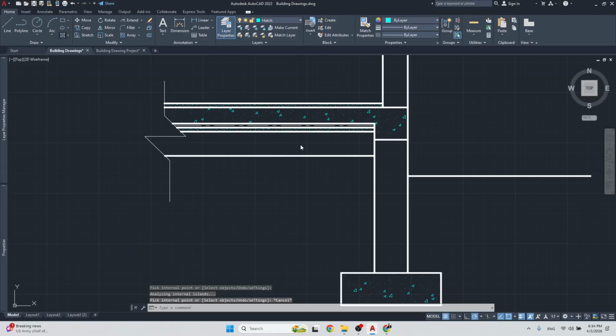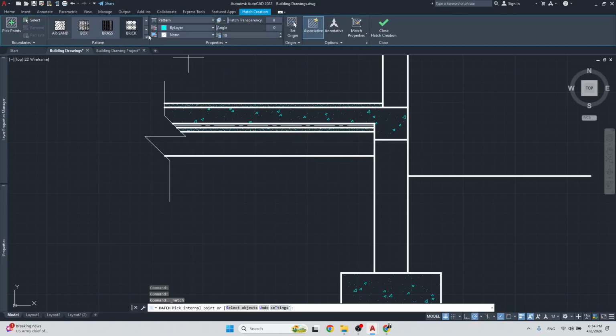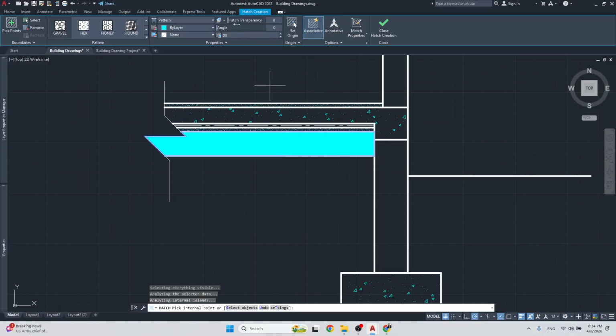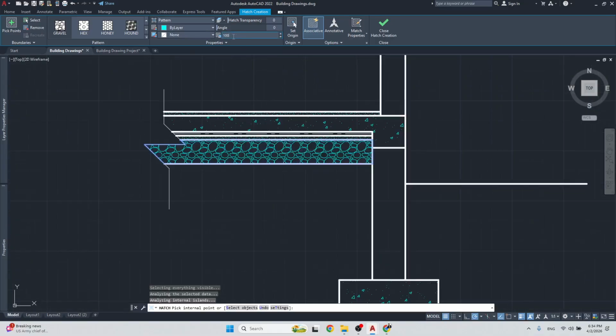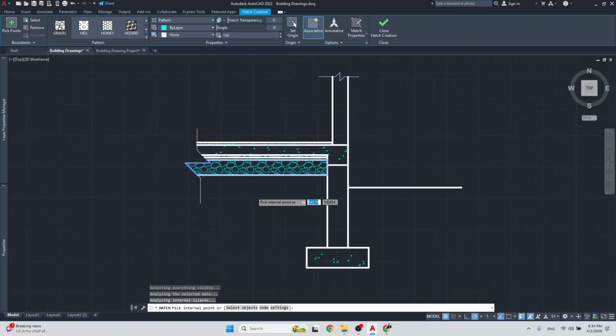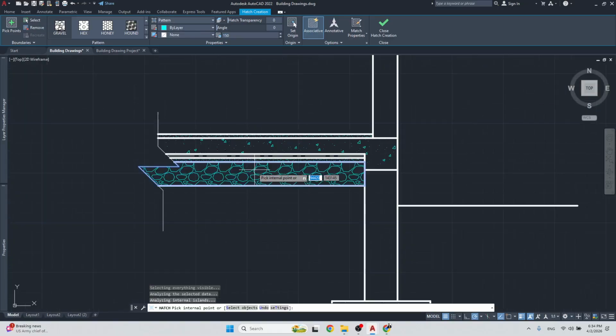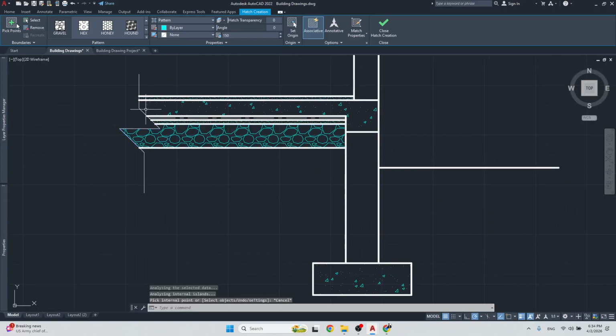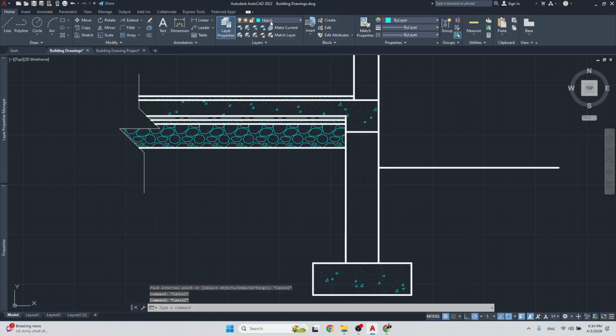So down here, which is the hardcore, we're going to use the gravel right here, and we might have to change this to, let's see, 20, how that looks. Ooh, let's change it, not 20, let's use 100 and see. Yeah, that looks alright. Let's maybe a little bit more, 150. Alright, that's good. So that's the gravel, the hardcore, and then underneath that now is going to be the earth. Alright, so let's switch back.